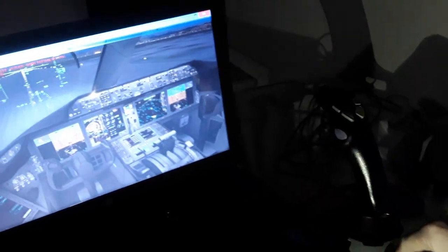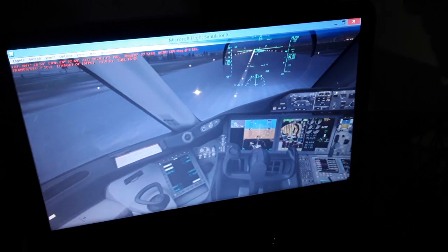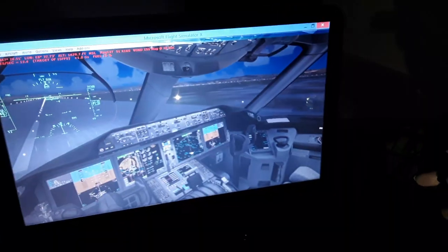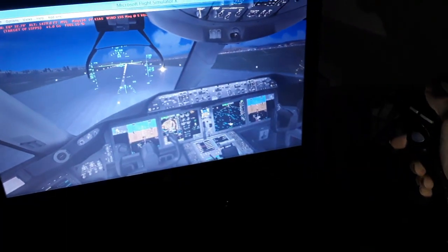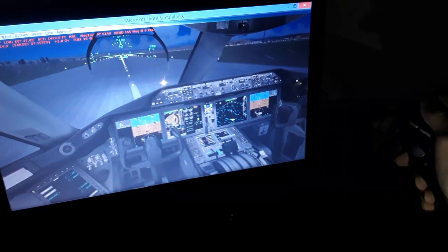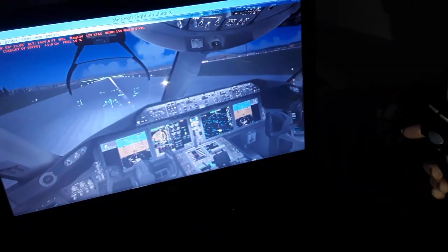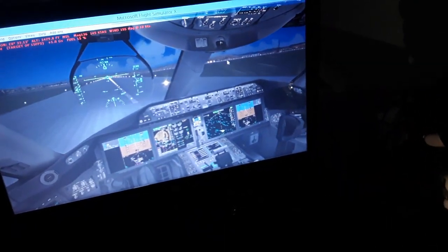Thrust levers to takeoff. Maximum takeoff, first stabilize. So we press the side stick down of the yoke until 80 knots, along the center line using the rudder pedals. So we have 100 knots. Also we're gonna rotate at V1, V2, we rotate.